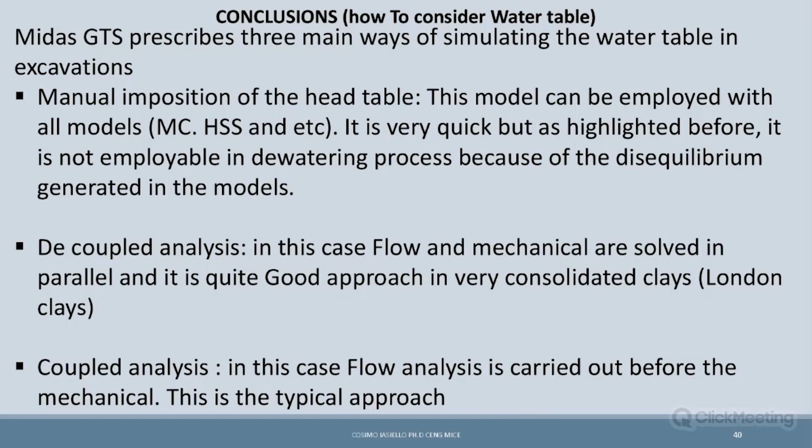Personally, when I am using Mohr-Coulomb for the coupled analysis, I experience problems of convergence, and I have to upgrade the Mohr-Coulomb to, I would say, a hyperbolic model like Hardening Soil or something else, because at the end of the day the yielding cap simulating the passage from saturated to unsaturated drainage is more acceptable for the program.